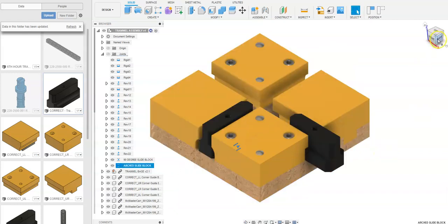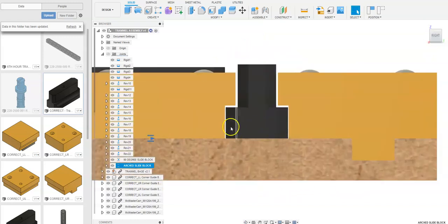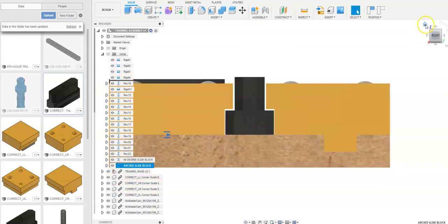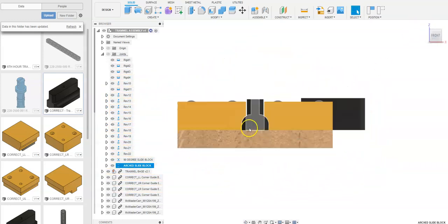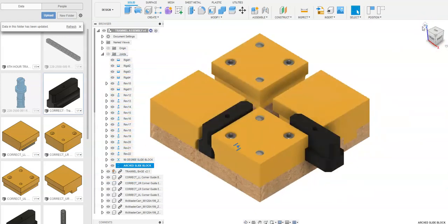Now, one of the things about tolerancing is we want to make sure that there is a gap in here. I can see air between each side. I can see that little white gap area in there. And our background's white, so we can see that. I want to see this arch in here. We don't want this to wear out. We've heard about parts wearing out before. We don't want that to happen. So you can see our little slider joint constraints that are left in here.